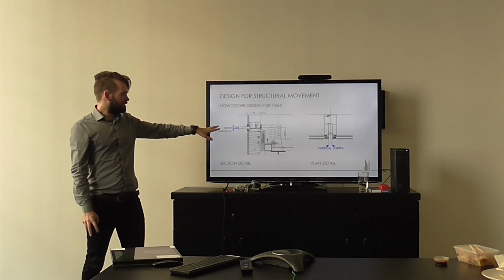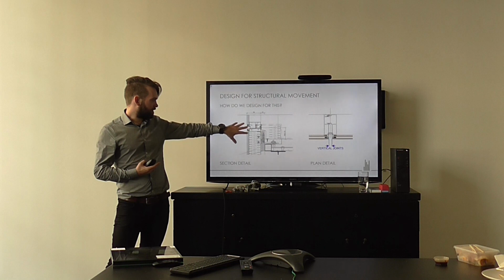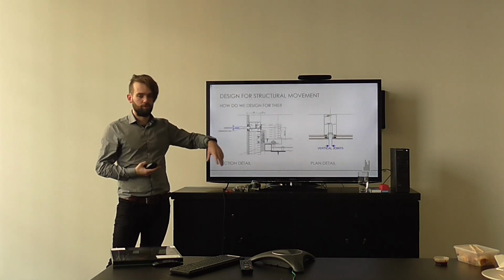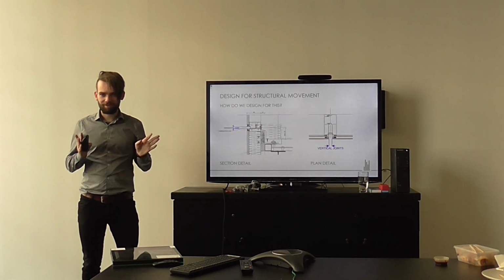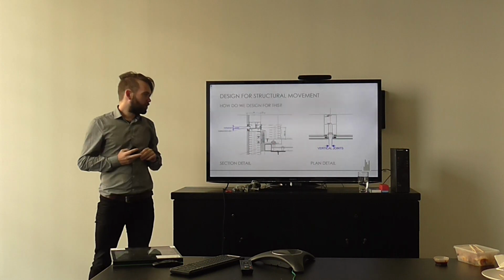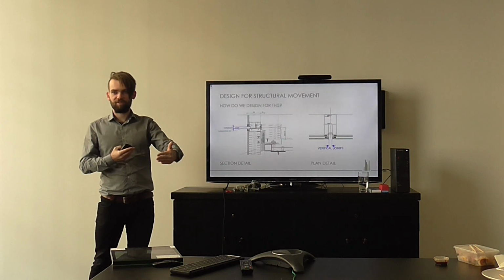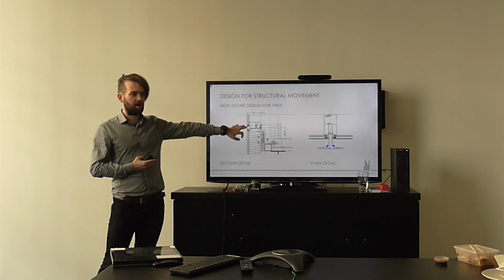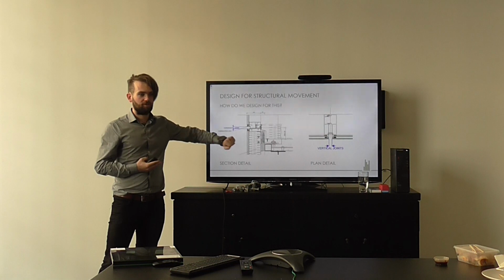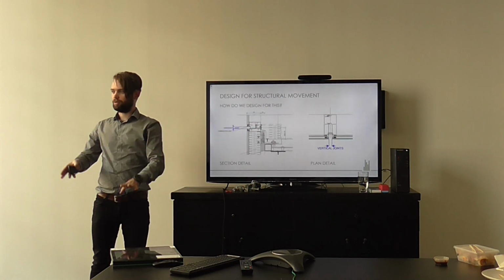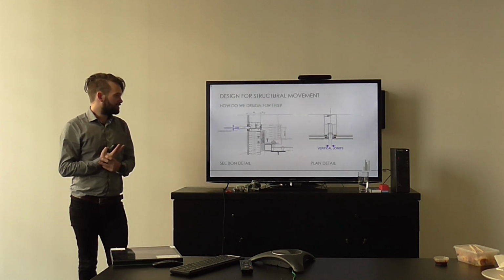So what it really governs is our joints. In this particular case, I've got a section and a plan detail which show the joints in our curtain wall. The back joint is typically smaller than the front. What those panel movements allow, behind a series of pretty serious computations, is to calculate the acceptable dimensions for this width, so that the panel won't accidentally come down too much and smack on top of him, or completely close or completely open so that you can actually see out onto the street.